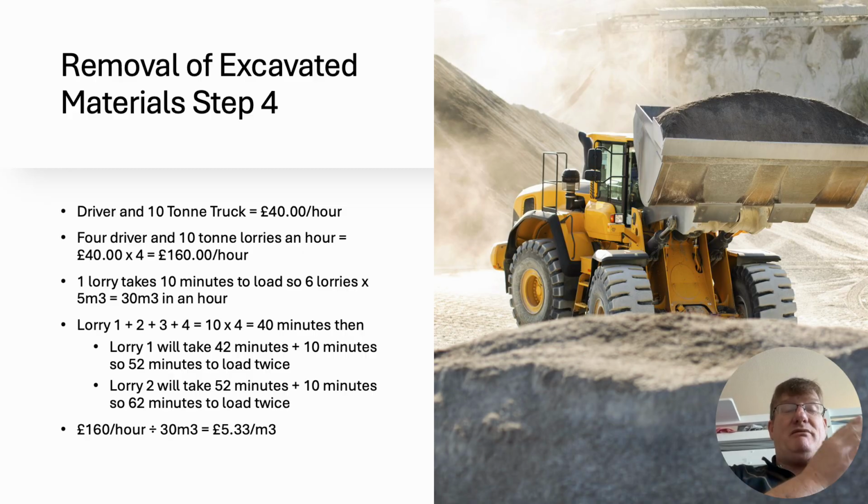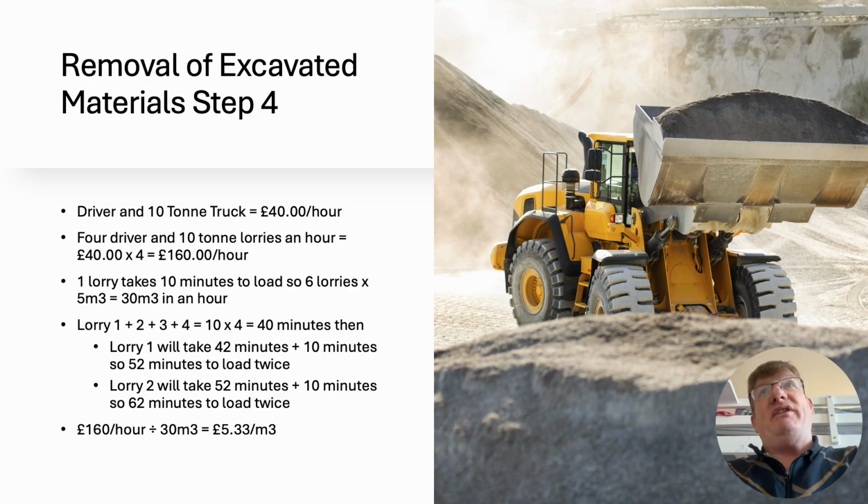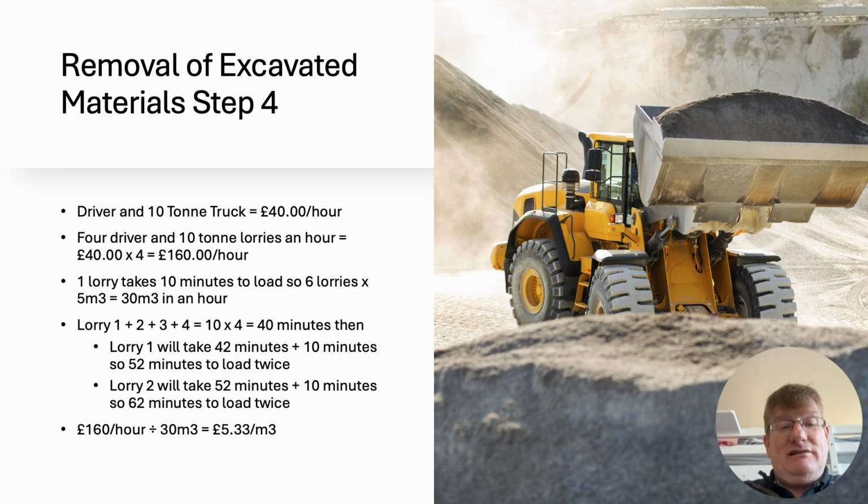Okay? But why haven't we got 6 lorries? Somebody asked me. We don't need 6 lorries because it's continuous. By the time that the first lorry has gone to the dumping area, the tipping area, and driven, they should be driving back and being reloaded. So there's your 5th lorry, if you like, and then as they've been loaded, your 6th lorry should be coming in on around the hour. Okay, so lorry plus 1 usually. We're saying it takes about 10 minutes a lorry to load, so that gives us 40 minutes really to load all 4.